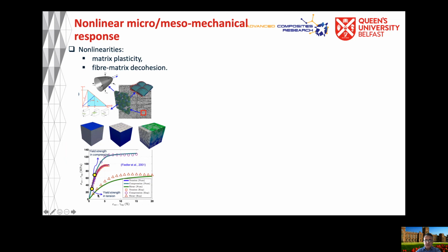And these figures show the validation of the plasticity model that we are using for the epoxy resin. So if we subject the epoxy resins to unidirectional testing, so unidirectional tensile load, compressive load, and shear load, again, we can validate that our simulation results are very close to the experimental results.